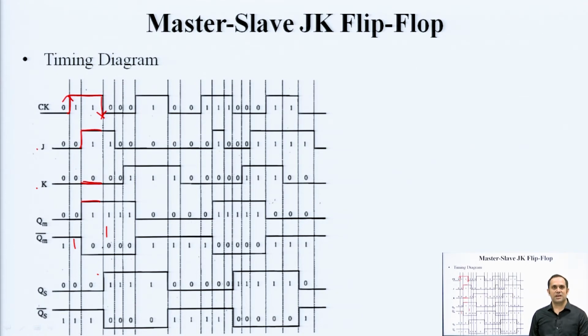Connect them in cascade in such a way that the output of the first serves as input to the next. Isolate the output from the primary input, isolate stage 1 from stage 2. In that case, you are updating your outputs only on edges, right. This way you are implementing an edge triggered device or register known as a flip flop, and this is the most primary storage element in any sequential circuit.